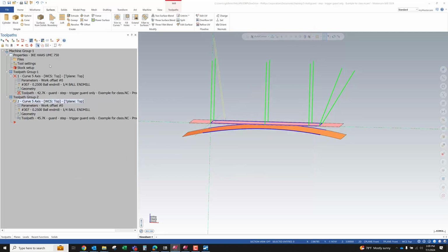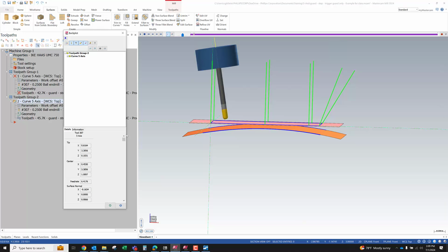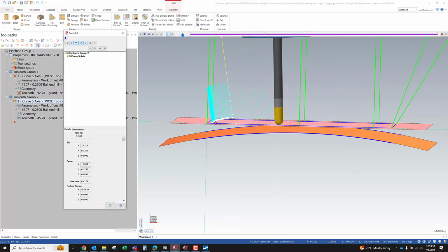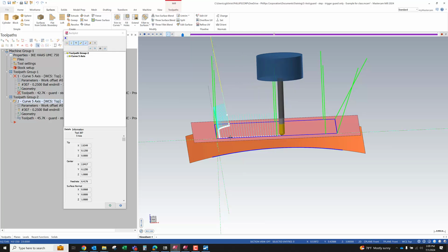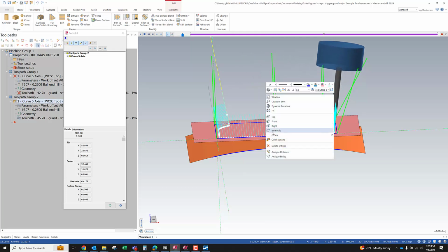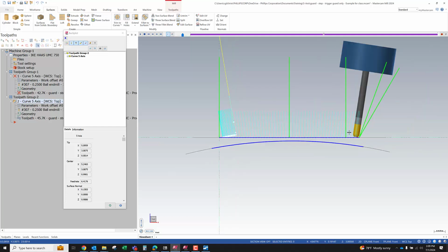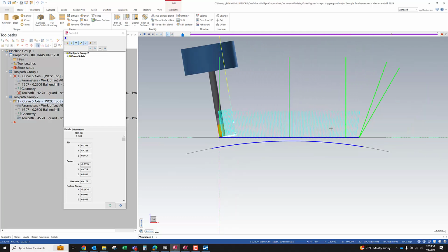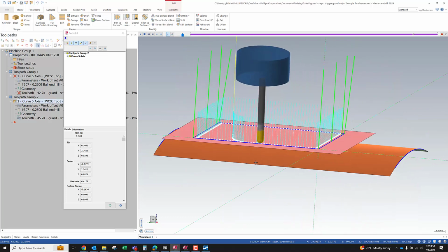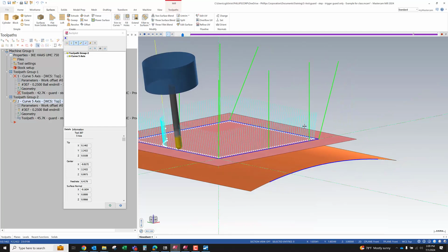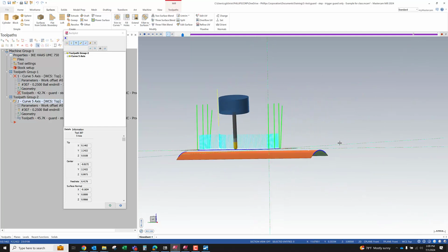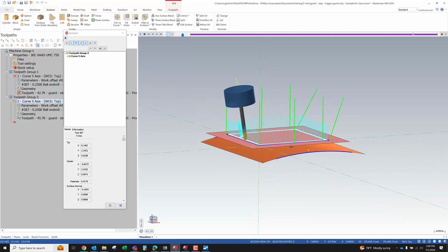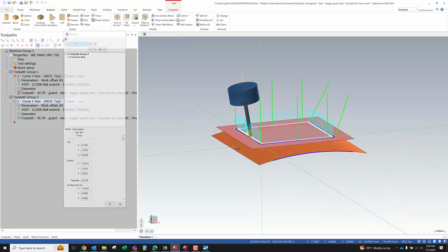So now what we generate instead, keep in mind what my input was. My input was a chain. And yet now I am using a surface underneath to control the angle of the toolpath. And that surface is only curved in one direction, so I would only expect the toolpath vectors themselves to curve in one direction and not to also rotate, unless my surface underneath was different.